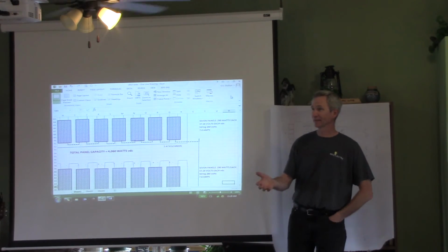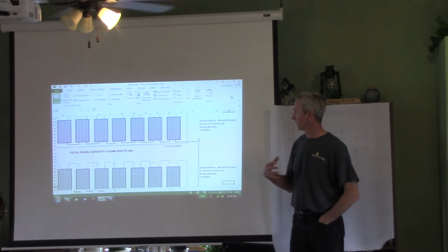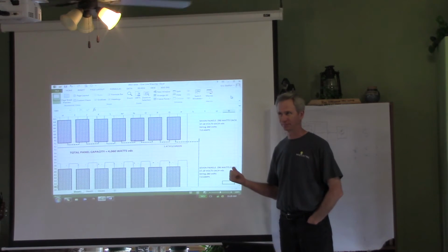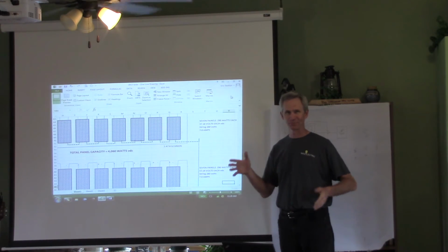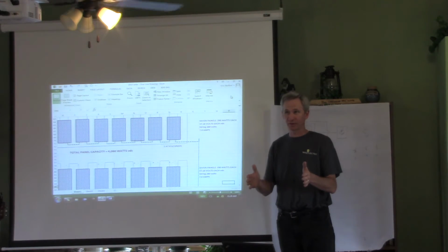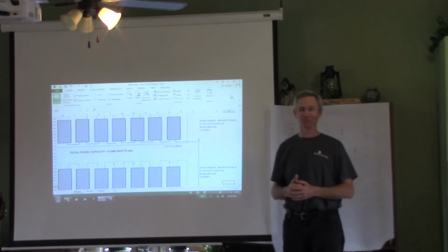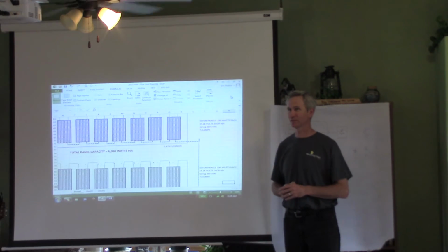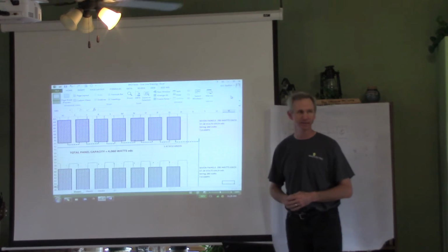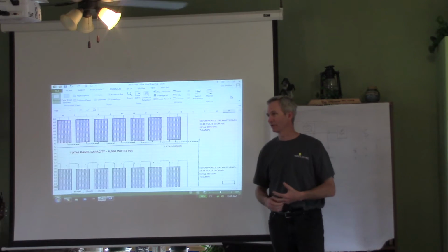So, I think this is the kind of thing where, building off of people's work, okay, here we did a 4,000 watt system. You want to tweak it a little bit, change it, but you could just stamp it, and it's pretty much gonna be the same thing. Now, if you want to go to an 8,000 watt system, you're gonna have to maybe get some more expertise in to design a system that'll work with those components. Or just put two of them in. Or put two inverters, right, take the same system and double it with another inverter, yeah.